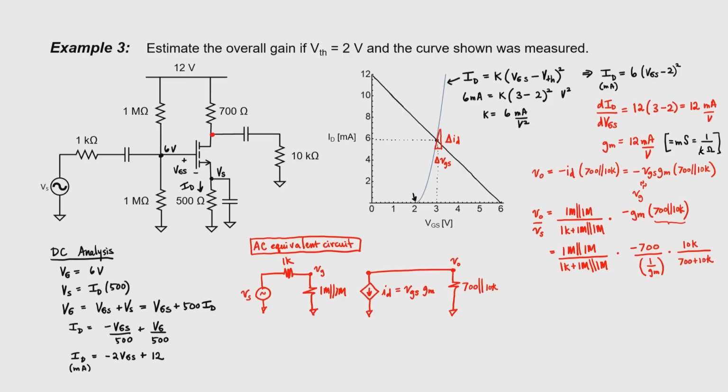The transconductance is just the inverse of a resistance. So down here in the denominator, we have some kind of a resistance. Let's call it little rs. And if we look back at our circuit, we can imagine that the MOSFET has a little R sub s right here, and it tends to be a small number, but we can't neglect it if we're grounding the source. So let's come up with a revised strategy for finding the gain of MOSFET circuits.